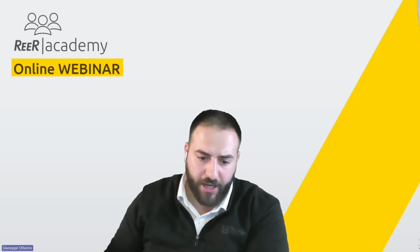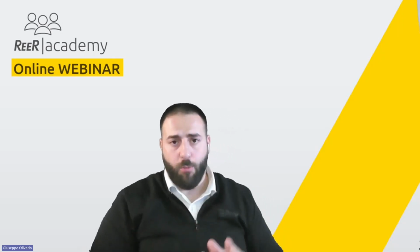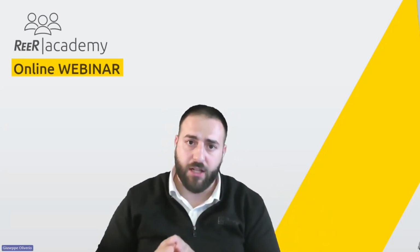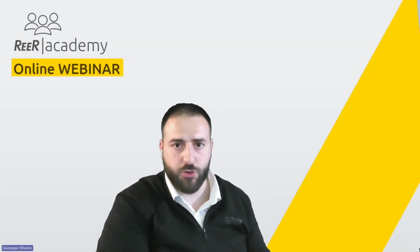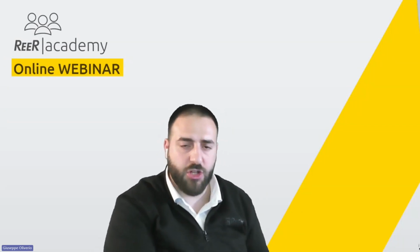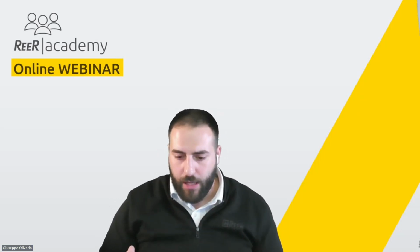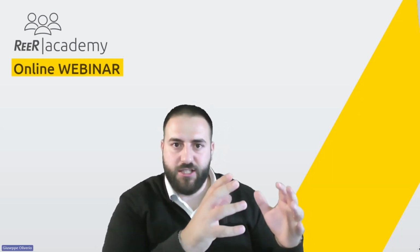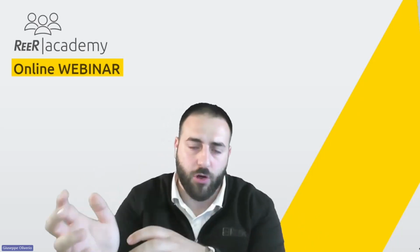Using the M1S COM connected with a Profinet PLC could be the same as using a ProfiSafe PLC? No, because Profinet is Profinet. ProfiSafe is a profile integrated into the Profinet protocol. So the way that is used in the ProfiSafe data exchange is different. But we are demanding the management of the safety function to a safety controller.